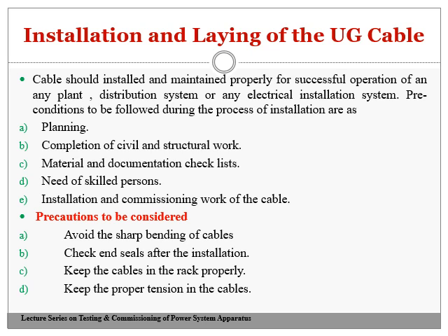Check end seals after installation, before termination or jointing. After installation, the end caps or end covers should be properly sealed to avoid the entry of moisture from either side of the opening. And if you are using many cables in a particular trench, always use a cable rack for proper installation and proper maintenance.